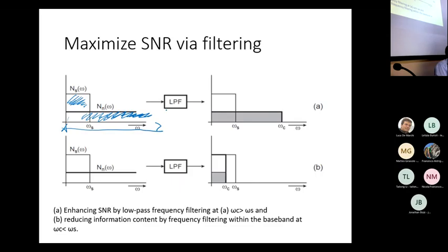So what we can do is add a low pass filter, set the cutoff frequency in the proper region depending on the maximum oscillation of the signal in terms of power spectral density, and then use the low pass filtering for enhancing the signal to noise ratio.